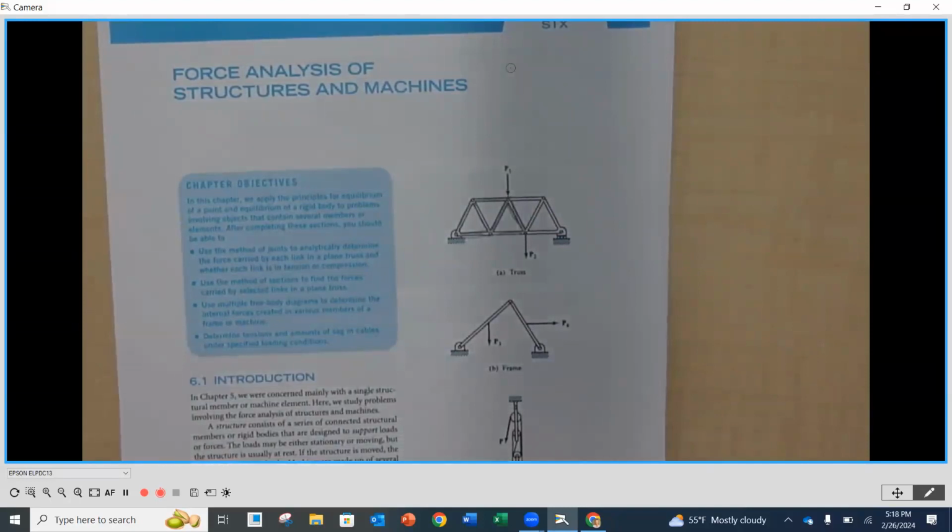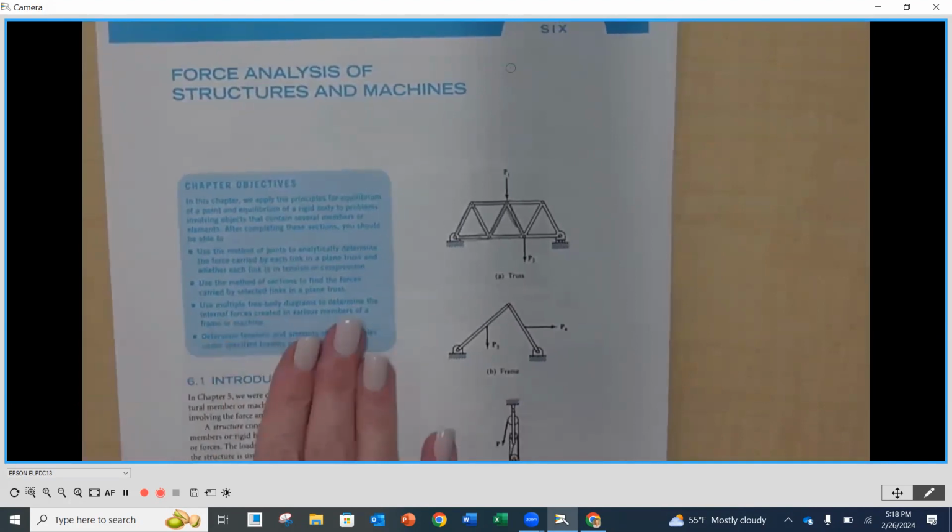Many materials can do something more in one direction, but not in the other. For instance, cast iron. Cast iron is a material that can take compression all day long, but you start pulling on it, it's going to crumble and pull apart in no time. Steel, on the other hand, can reverse load and pull and push in both directions almost identically. Okay, that's why it is a very nice material to work with.